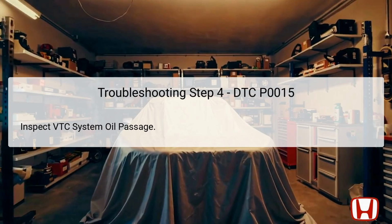The fourth troubleshooting step is to inspect the VTC system oil passage for debris or clogs. This passage is essential for allowing oil to flow from the pump to the VTC components, including the actuator and solenoid. A blockage in this pathway can significantly impede the operation of the VTC system, leading to erratic timing and ultimately triggering the P0015 DTC.